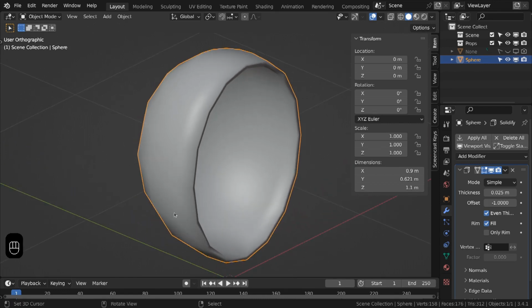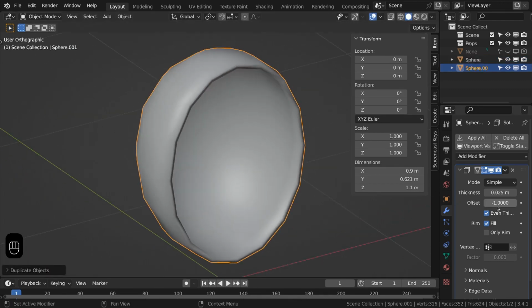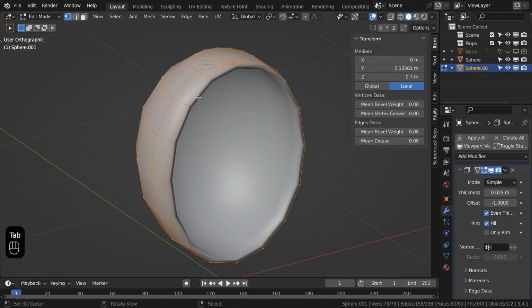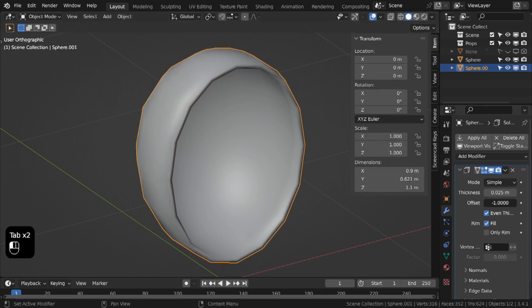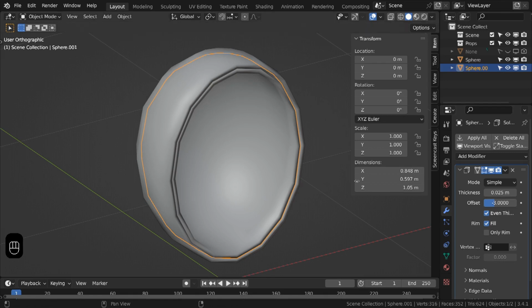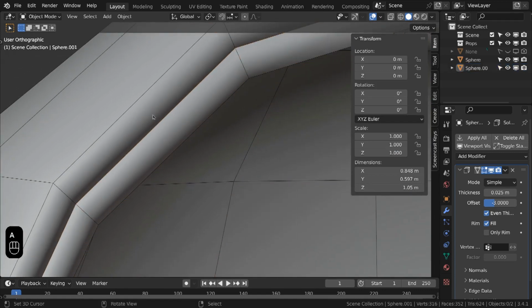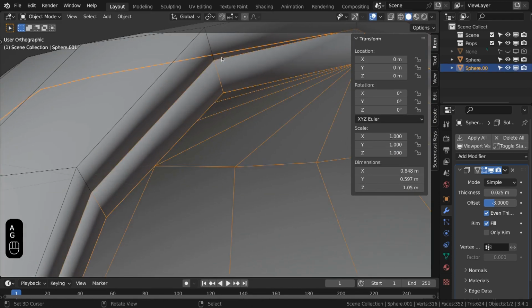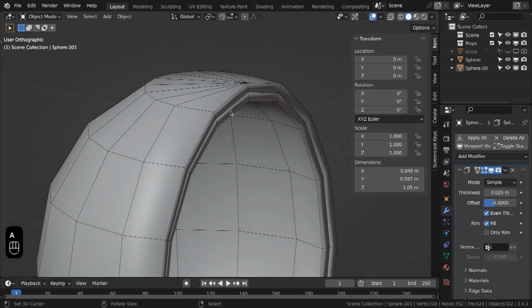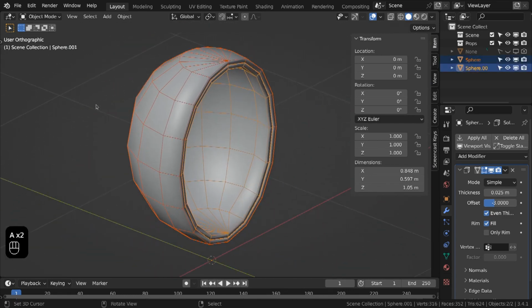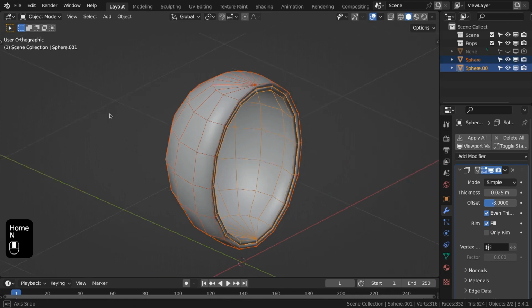And now the chair has an outer and inner shell, so we will duplicate it. And to move it inwards, we will use offset. As you see now, it's -1, meaning it goes on the negative side of the normals. But the thing is, it's not bound just from -1 to +1. We can write -3. And if I now enable wireframe, you can see they sit perfectly together. So yeah, that's it.